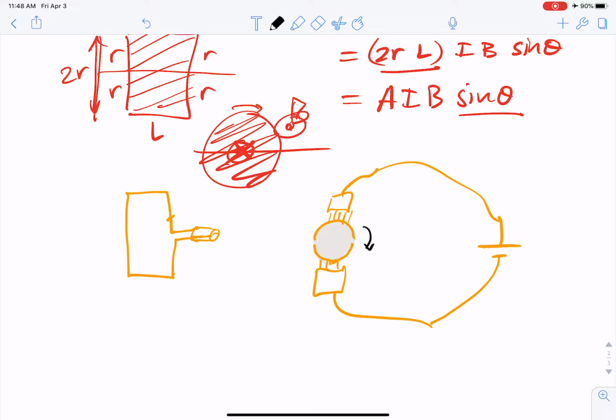So as it rotates, I suppose this is the unstable one. It's going to rotate 180 degrees. The coil will rotate, and it carries, this is on the axle, right? The axle is mounted on this thing. So as it rotates, these guys rotate too. And if you see what happens is it gets to some point where these brushes are connecting to this, connecting to that, but as it rotates enough, it no longer connects there, it connects to the other one. And so then the other is essentially like running the current in the opposite direction, which is exactly what you wanted.